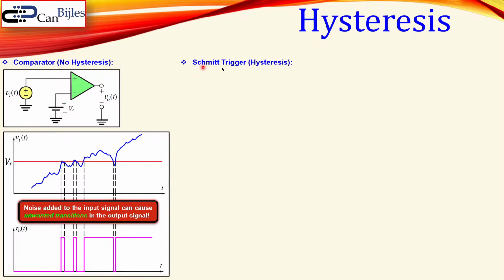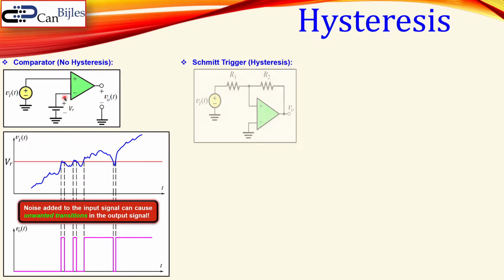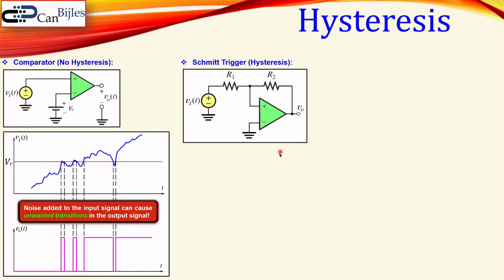We can use the Schmitt trigger circuit. It's called the Schmitt trigger, which has this hysteresis, which is sort of a safety region where you actually want to trigger, but you go a little bit up and a little bit down, and you create two threshold voltages instead of one reference voltage. And now we can create here the Schmitt trigger circuit having a hysteresis. In this case, the input node voltage is always compared to the ground voltage, which is 0 volts.